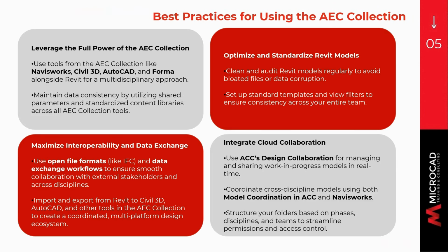Use your ACC's modules to manage versioning, track versions, changes, and share progress across teams. Also, structure your ACC folders strategically. Set them up by project phase, discipline, or role so you can control access and keep your workflow organized. And well, these strategies, using the full AEC collection, preparing your model properly, and managing collaboration smartly, set the foundation for efficient integrated workflows across Revit, ACC, and the AEC collection.